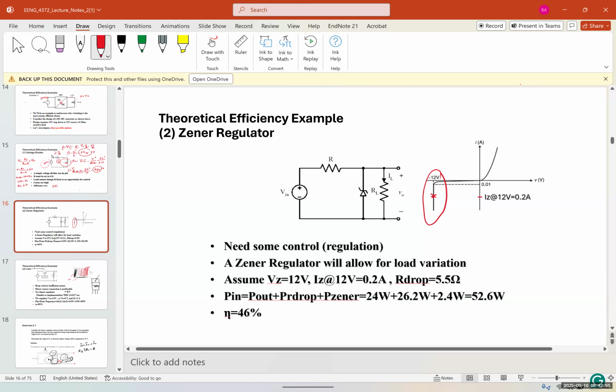So you can see that a Zener diode is also not good at all, hovering around 40 to 50%. But usually we don't want to divide the power in half. If we have an input of 9 volts, we want the output to be around 8 volts or 6 volts. So the efficiency could technically be higher, but again, we have this limitation of generating a lot of heat and low efficiency.